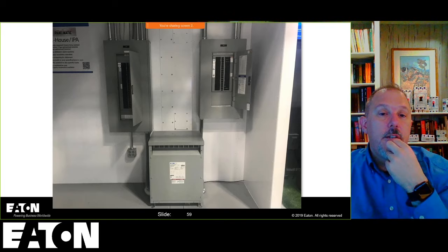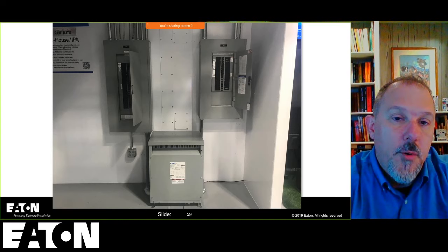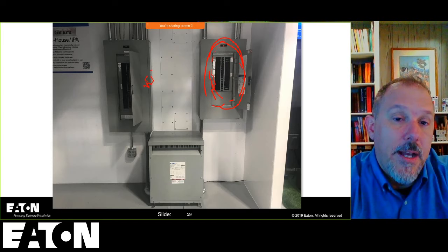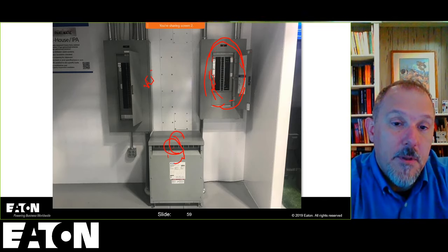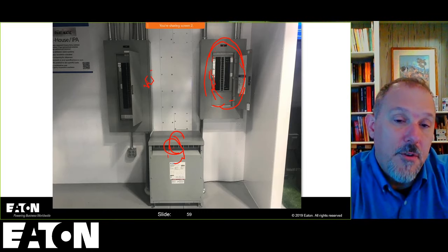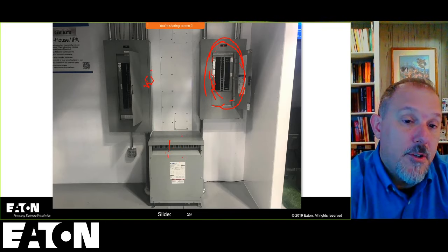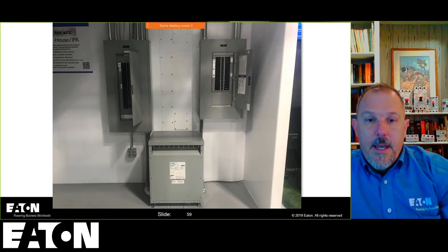It could. I could argue that knowing which one of these breakers actually turns off that panel board also adds a little confusion, because you've got maybe 15 different options here to de-energize that transformer. And over here, if you label it correctly and give the proper indication, you have one solution and that's it. So I could argue that both ways, but I definitely understand your point. Okay.